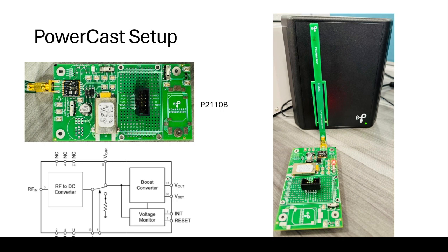Now, the harvested energy is thus supplied in intermittent cycles, which resets our microcontroller every time the power goes off. Thus, we need to save the intermediate state to resume the execution correctly after every power cycle. So to do that, I have used the external flash memory connected on the Metro M0 Express development board. The external flash memory is a non-volatile memory which will store the intermediate state of my program, and once the power comes on again, we retrieve this information from the flash memory using SPI and start the execution from the intermediate state instead of starting right from the beginning of the cycle.